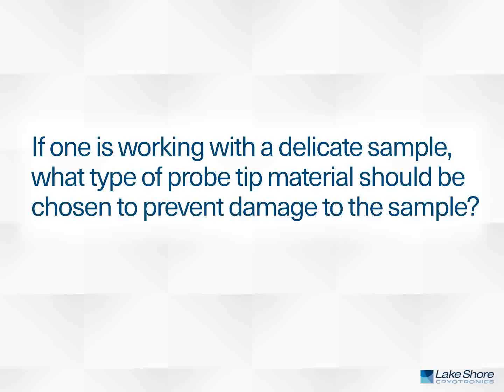We offer, I think, three different kinds of probe tip material. For delicate, softer materials, I'd recommend our beryllium copper probe. It offers conventionally the lowest contact resistance and basically the smallest amount of damage to the contact metallization. For contacts like aluminum and other materials that develop oxides, as we discussed during the presentation today, that's where you have to use the tungsten probe to punch through the oxide material.